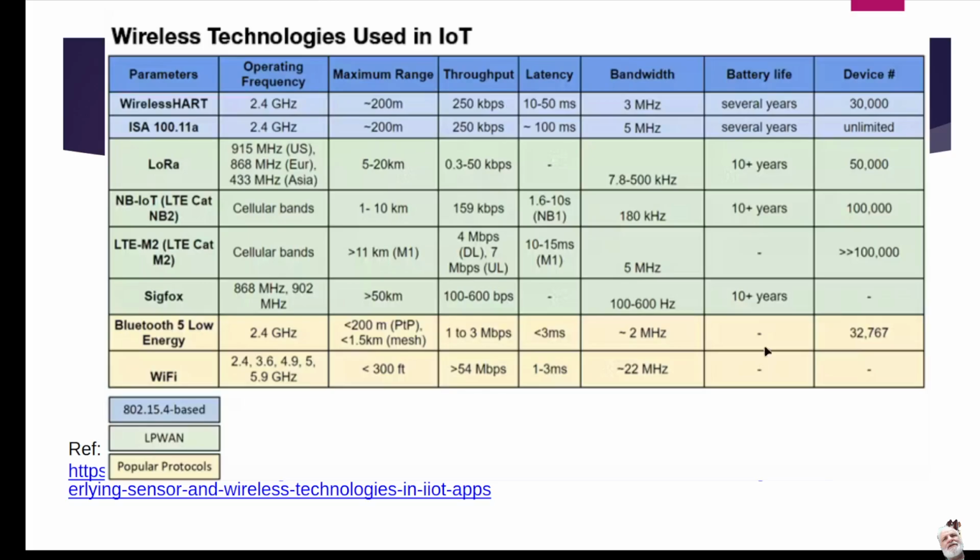but they cost you in energy on your device to send that data, whereas LoRa and some of these other ones listed here are very low power. They can't send a lot of data, right? The amount of bits per second they send is really low, but because they're only sending a few bits and they're very low power, you can run them off a battery at a remote site, and that battery can last for quite a long time. So that's all we're trying to demonstrate with this slide.